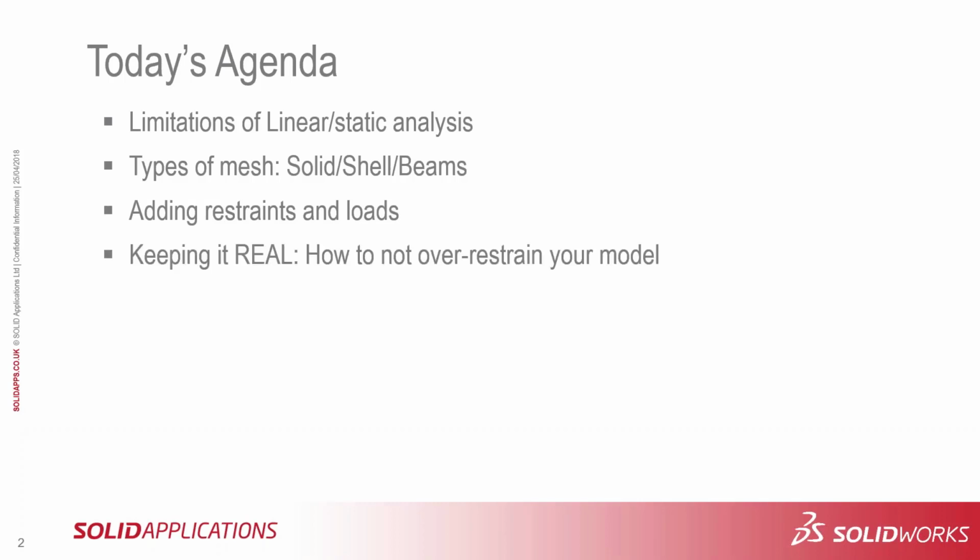Keeping it real: how to not over-restrain your model, because it's very easy to say, well, I'm just going to restrain this face and that face and that face, and that may not be realistic. If you over-restrain your model, you're not going to get accurate results, and you're certainly not going to get conservative results. So we want to go over a little bit of how we think.